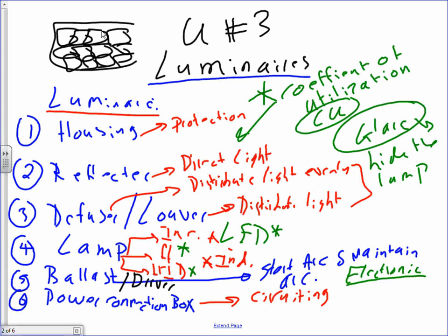To cut on the glare, we use diffusers and louvers. That's the method of cutting on the glare. Can I have thumbs up, Chad? Diffusers and louvers cut on the glare, and when you do, it makes you and I feel comfortable under the light, which is a goal. Then there's also a concept called coefficient of utilization.